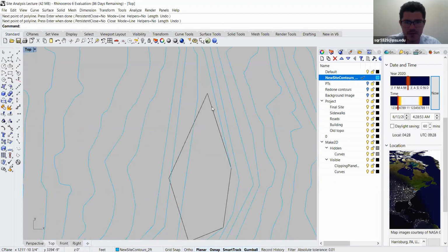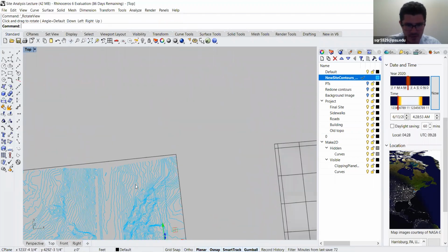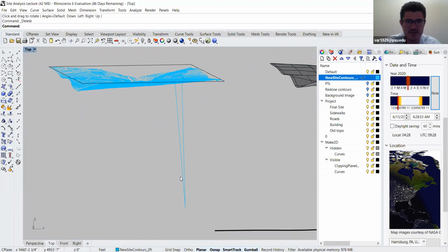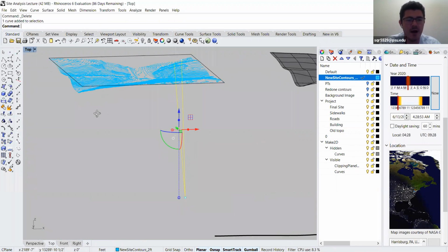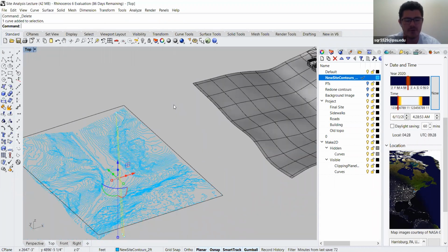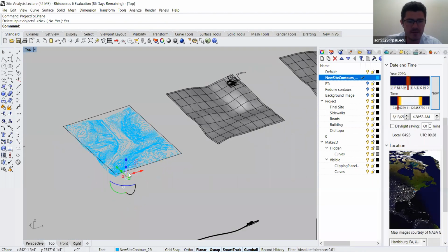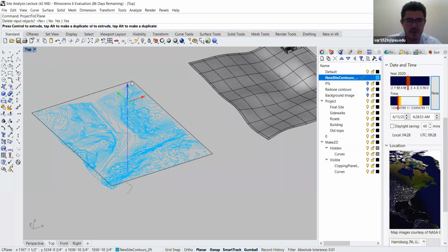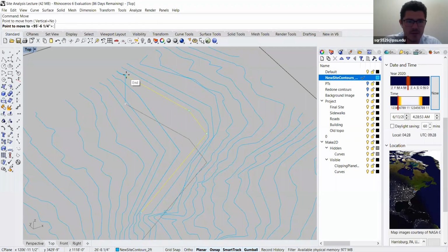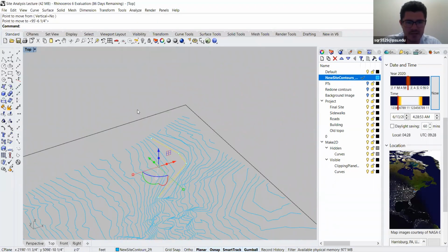So one thing I do want to check is, when you draw, and these are all in 3D, you can see that this happened. You can see it snap to something. One thing you can do is set it to C-plane, or project to C-plane. And yes, you can delete it, and then it will flatten your draw line. So that way you can bring it back up and match it to your contours. This can happen a lot in Rhino when you draw in a 3D sense.